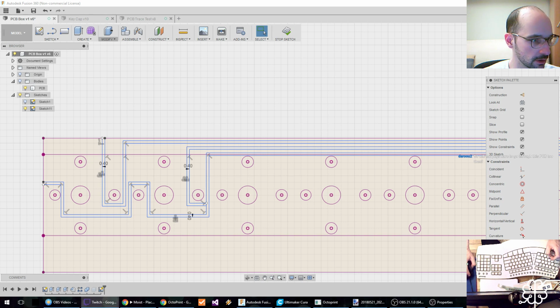Let's just keep going. So Daryl asks, will pegs have to go through the PCB too then? Yes, they will. But the reason for that is because when you've got, this is the top of the PCB, I need the metal peg to stick through just a little bit so that I can solder to it from on top onto the copper. Now, because we saw earlier that the metal pegs are the same length as the plastic pegs, both are going to stick through together. So you're absolutely correct in thinking that the plastic is going to stick through the PCB, which is a bit unfortunate. If both were separate lengths, then that wouldn't be a problem. But yeah, there you have it.